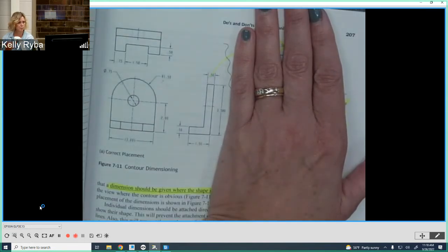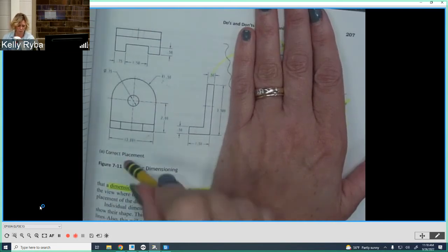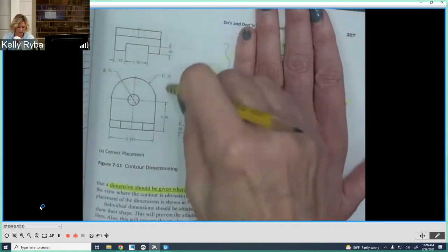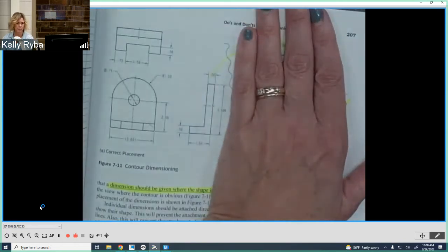And if, for instance, you change your 1.5 inch dimension to 2 inches, now I know this is Creo, so it's a little bit different because the dimensions are parametric and they go along with the features, but potentially it could get forgotten to get rid of that 3 inches. And you just don't want that to happen. So it can cause confusion if they're not updated, okay? So I always err on the side of asking, do I really need a reference dimension? Unless it adds clarity or somebody is requesting it, then maybe I'll put it on, but other than that, no.